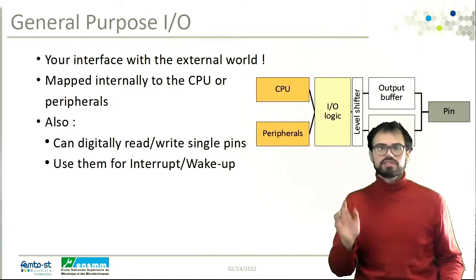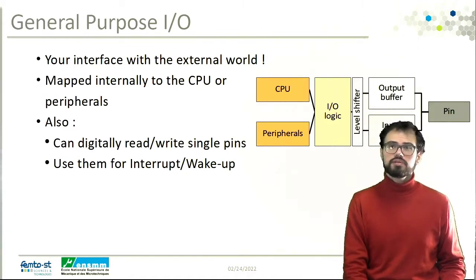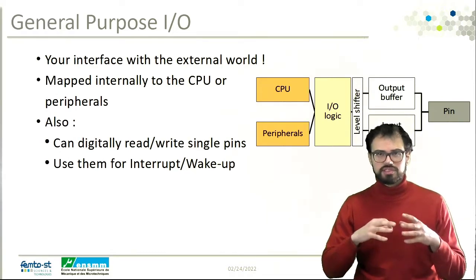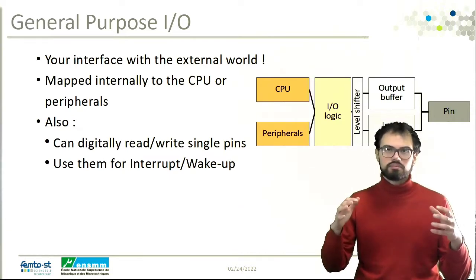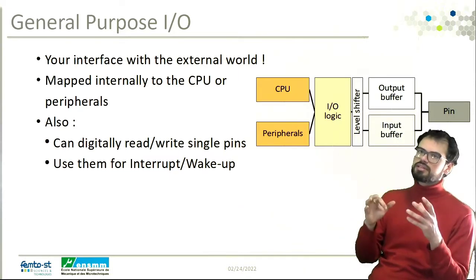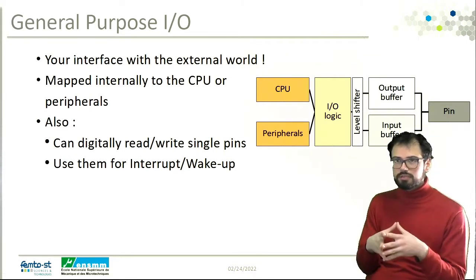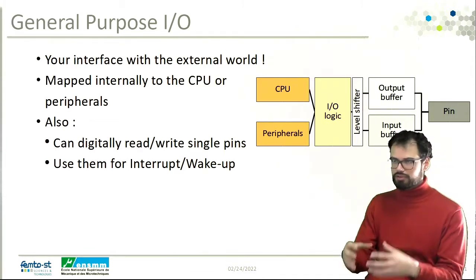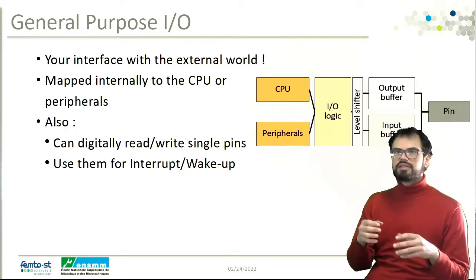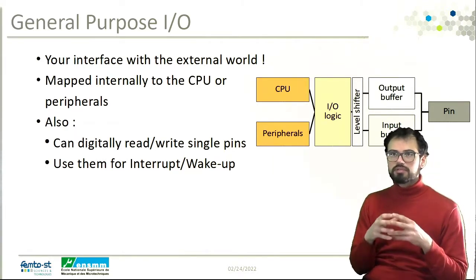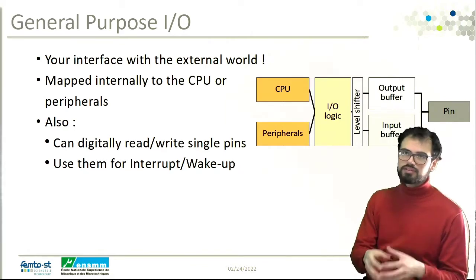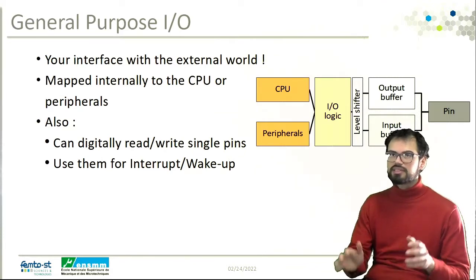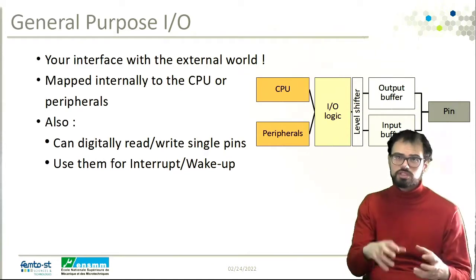Then we see about your general purpose input-outputs. They are your interface for everything that is outside your microcontroller. They provide an input and output for electrical signals, and you can access them by the pins on your microcontroller. You have input and output buffers that are governed by software, and then you absolutely need a level shifter to interface with especially the digital portion.